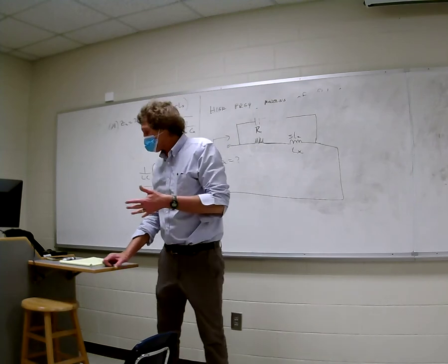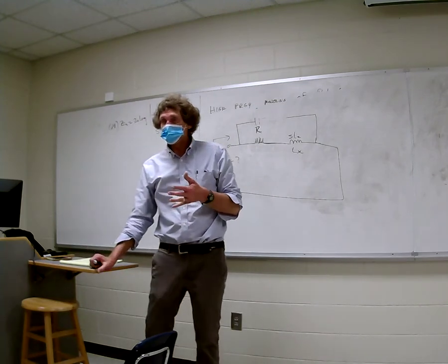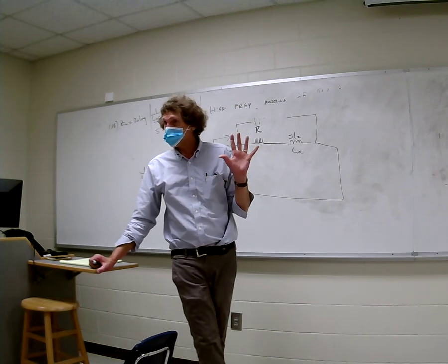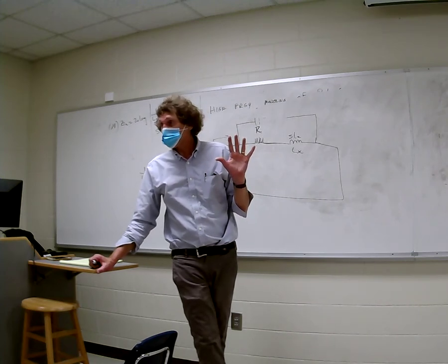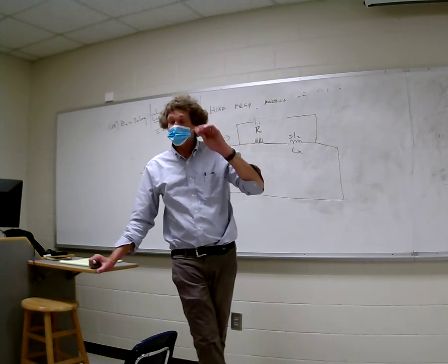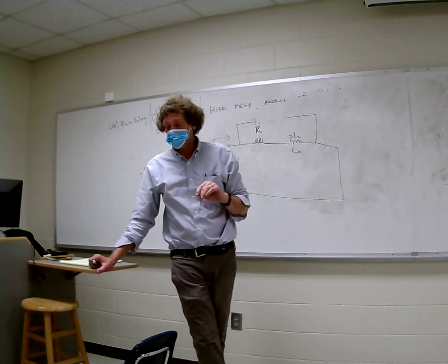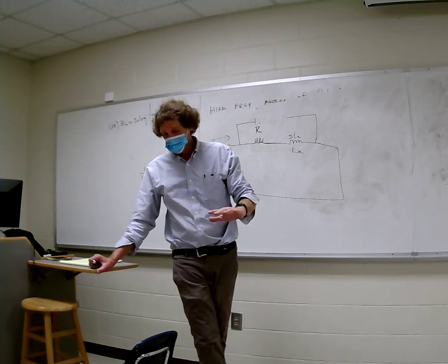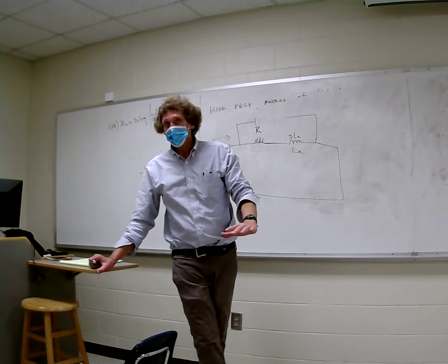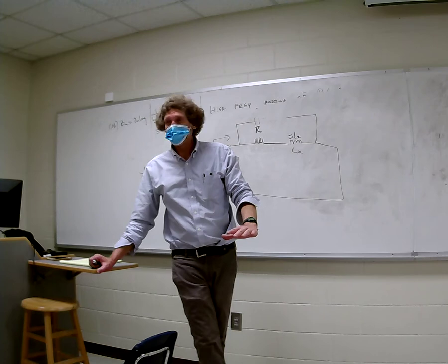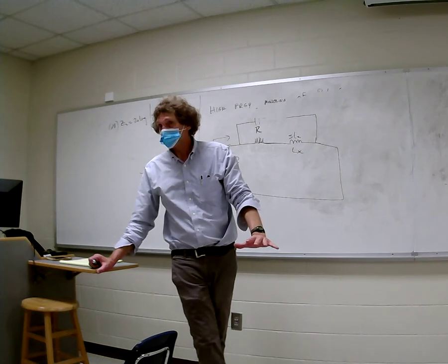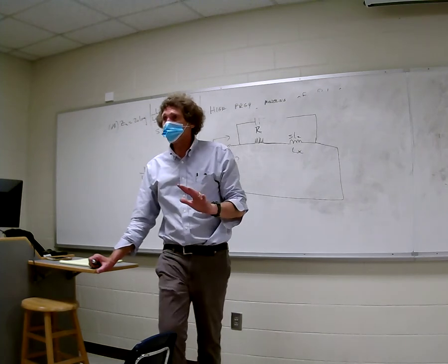This I'm going to talk about from a personal experience. I worked on a railgun years ago here, and even though I didn't deal with this capacitor, they had high energy capacitors. High energy capacitors at that time were electrolytic. Since I think they have some that aren't, they're much more energy dense and lighter. Well, I'm going to say they're about 250, 300 pounds a piece. I think it was 33 millifarad, which is enormous because they could withstand 10,000 volts. That's a tremendous amount of energy. I could be wrong about this, and maybe only be 1/4 of that.